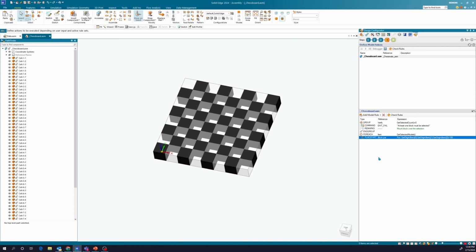So now I've specified this part, and now what I'll do is select a face style. So I'll go to parameters, select a face style, and let's say for example I want to paint this red. So I'll do Rosso, and this is going to be when the condition is true. And like I said in my previous presentation, a for loop has to end with the next loop. So when I go here under workflows and select next, it ends this loop.